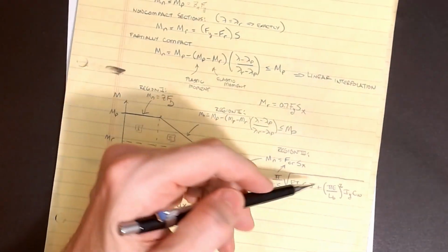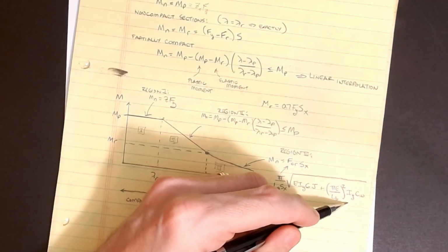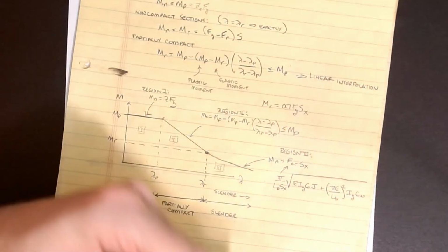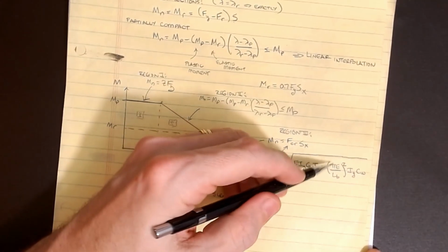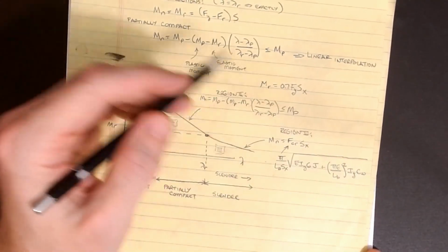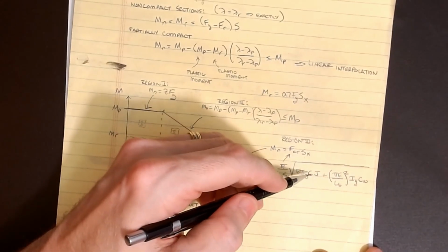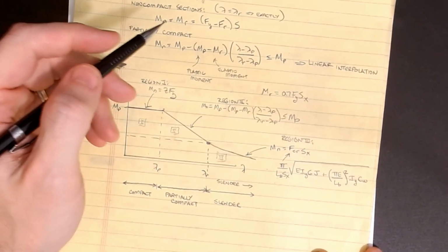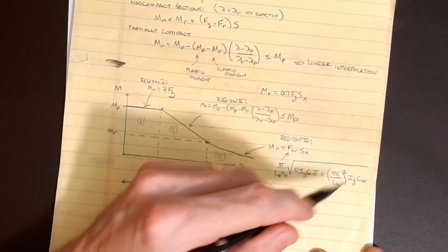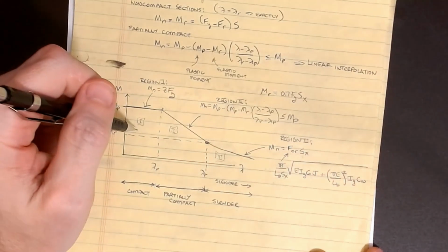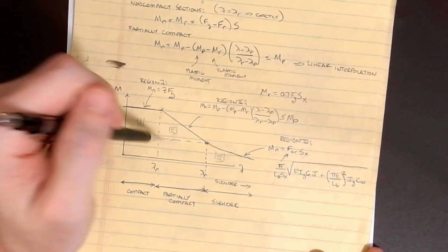There's a whole lot of other terms that go in. You've got a warping constant, you have a buckling about the x-axis, but it's got a moment of inertia about the y, because the beam is now so slender that it's starting to roll over on itself. We've got a pi squared thing happening, so there's a buckling-like term in there. And then I've even got GJ, which is a polar moment and a shear modulus running around. So this thing is all kinds of confused. If you're in my class, we won't be doing anything with that. We're going to be trying to design mostly in region 1 and region 2. But you still have to understand how to figure out where you are in this.